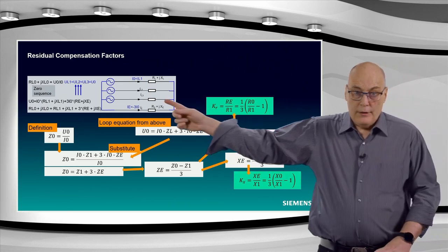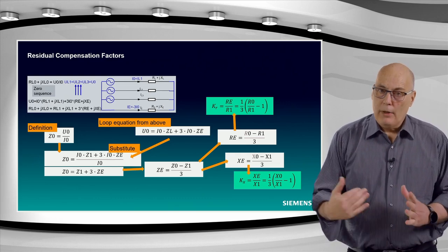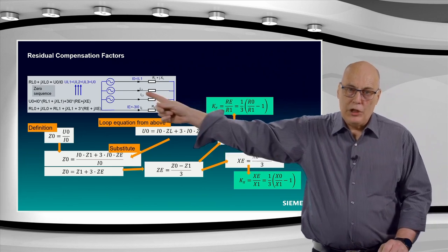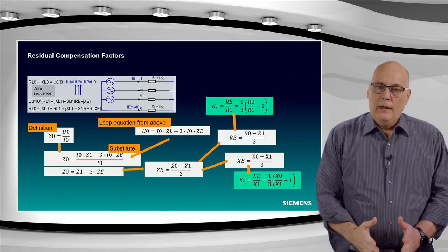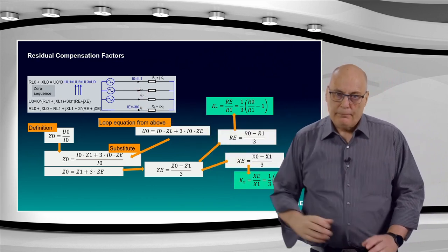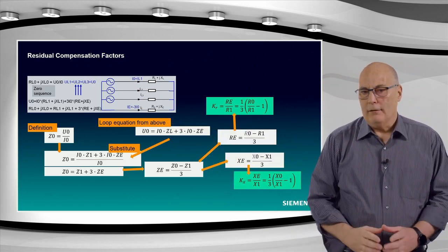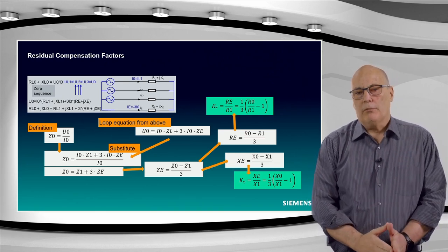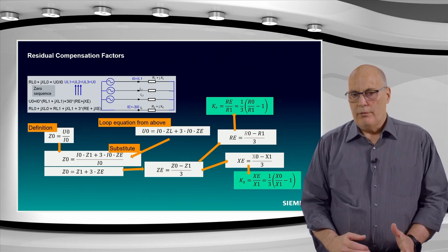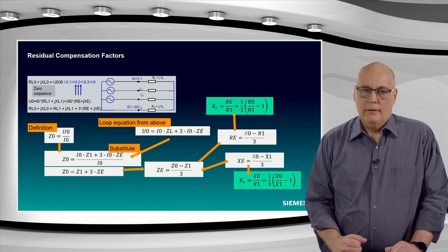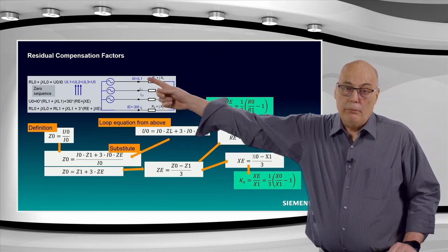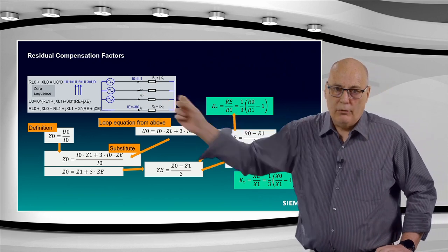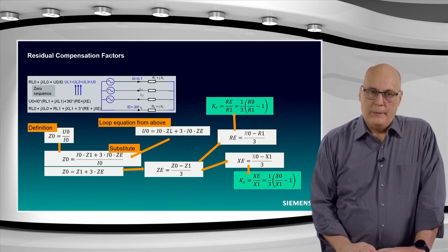So what am I trying to show in this diagram? In this diagram here, I connect my three phases with a short circuit at the end of the line, so to speak, and I inject at the beginning 3 voltages, and the 3 voltages I inject are those 3 blue arrows. They are exactly in phase and identical. So in that case, what voltage is that? That is the zero sequence voltage by definition. The zero sequence voltage means that it is exactly the same in all 3 phases, magnitude and angle. What you could do in this case is make a short circuit here, because the voltage there is identical, and replace that injected voltage with a single U0, zero sequence.